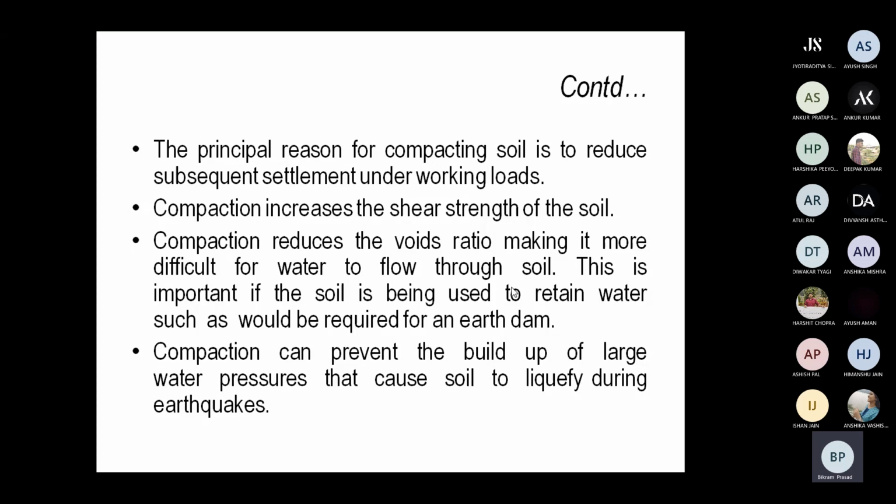So you can see by compacting the soil, most of the engineering properties are getting improved. If we can compact the soil properly, for the foundations we will be using, we need not go for big mat or raft foundations, or pile foundations. If proper compaction is done, the settlement will be less, and you can see that settlement is very dangerous for our construction work.